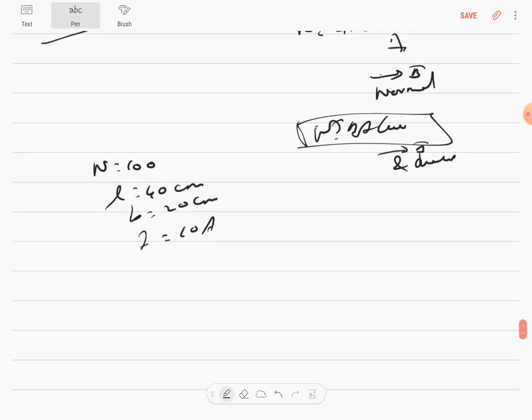What I am teaching is what you should stick to for the solutions. So theta itself is 60 degree. Torque itself is NIBA cos 60. Some might have put sin 30 because cos 60 is nothing but sin 30. That's confusing, but you know that when it comes to the angle between the coil and the magnetic field, you'll use NIBA cos theta. Directly you put 60 here.